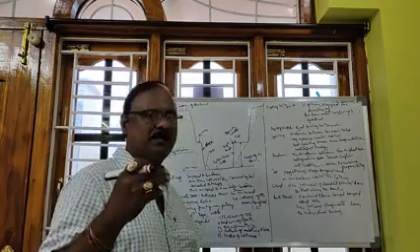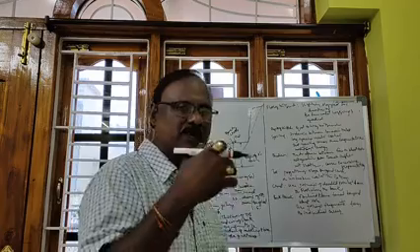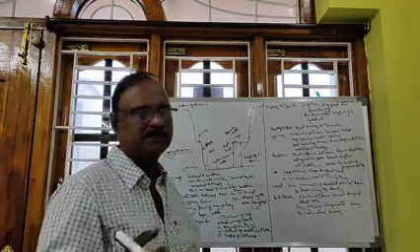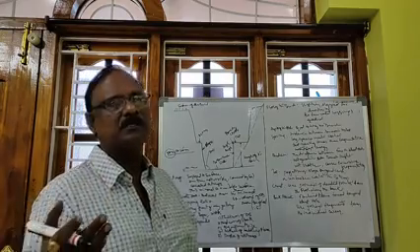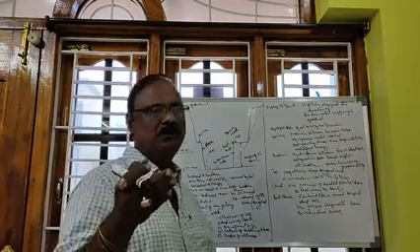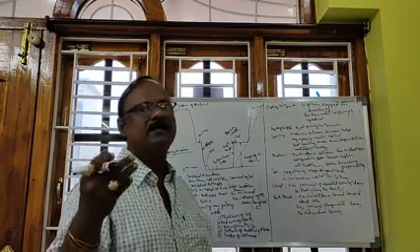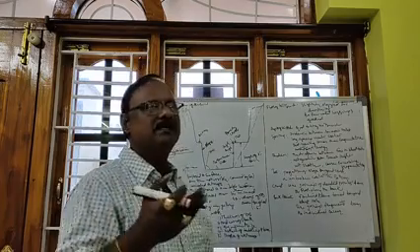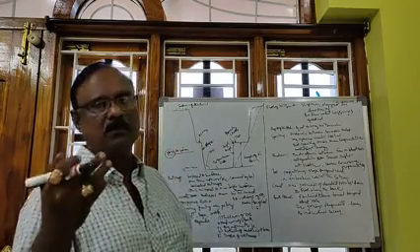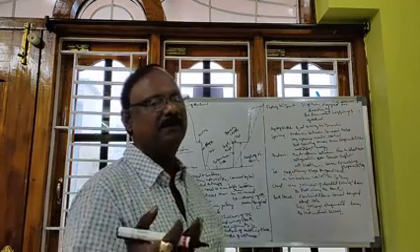In a similar fashion, the coal is available below the 50 meters. Suppose a 20 meters coal seam is there. The 20 meters of coal may be converted into different benches. The height of the bench may be, suppose, 10 meters. 10 meters means two benches are created there.